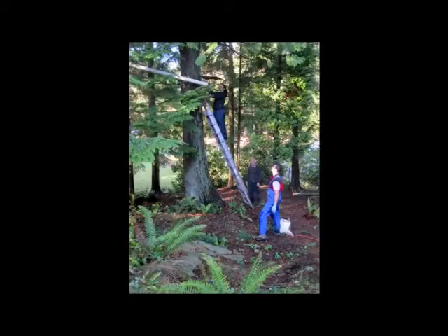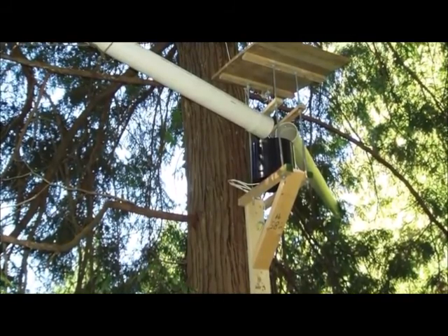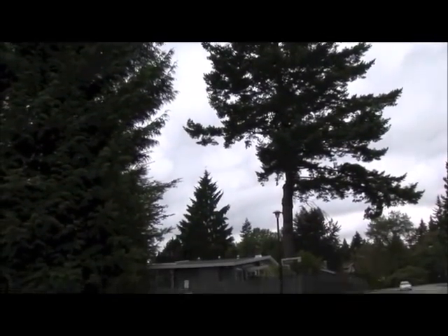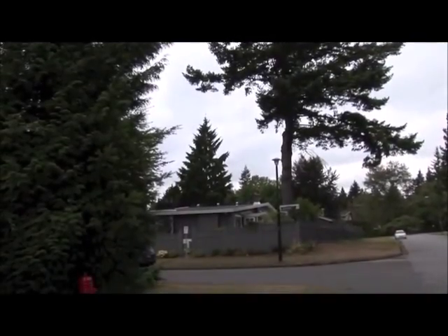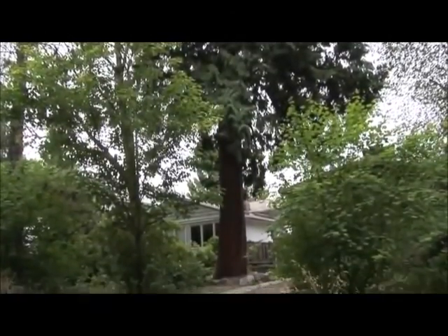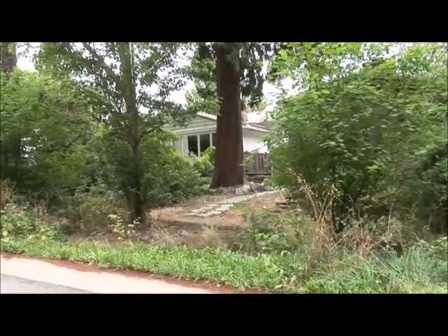Research has shown that western red cedar trees intercept and evapotranspire up to 55% of rainfall. Even without other stormwater designs, a large tree can slash your effective impervious area. Urban trees also provide shade, temperature regulation, windbreak, erosion control, wildlife habitat, and they act as a carbon sink.